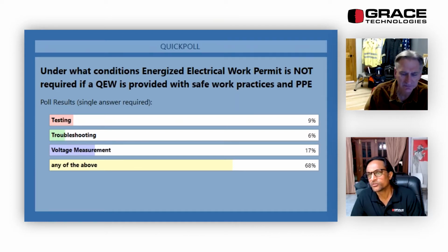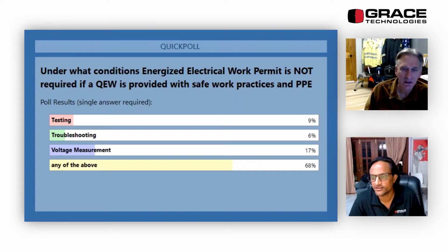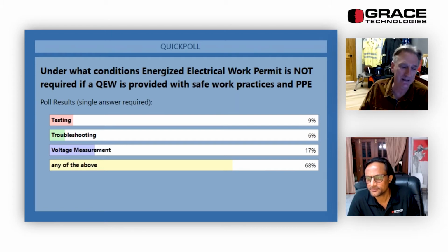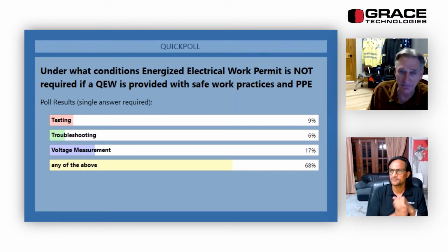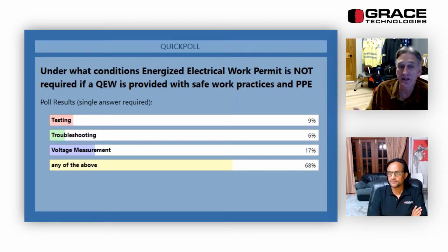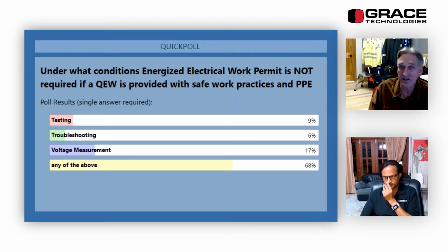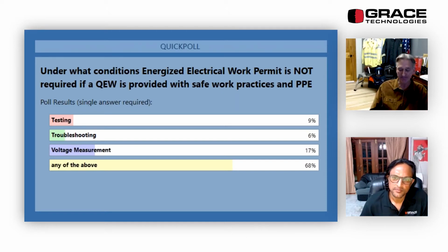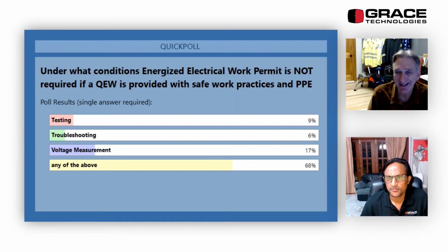Okay. So what about touch-safe equipment? All right. So in this finger safe or touch safe, there are disconnect switches out there that are designed so that they are finger safe and touch safe. It would be up to the company, up to the facility, to do a study and determine if that would be safe for them or not.